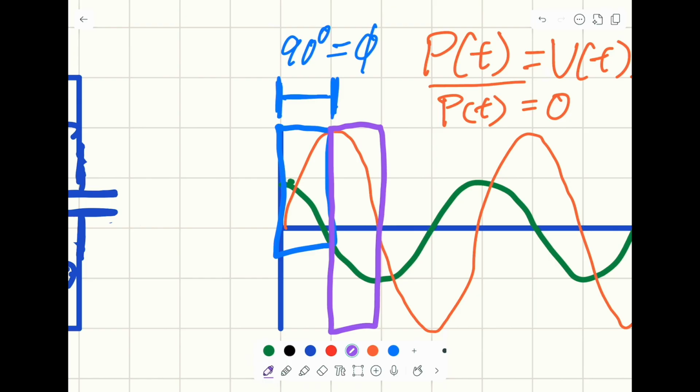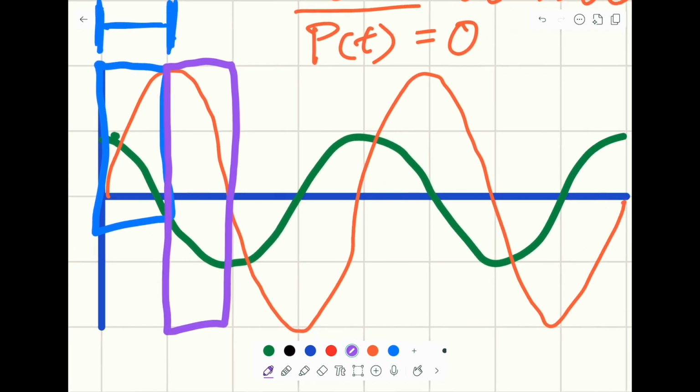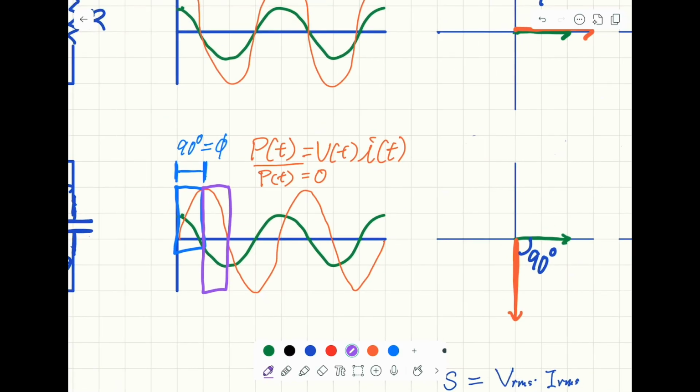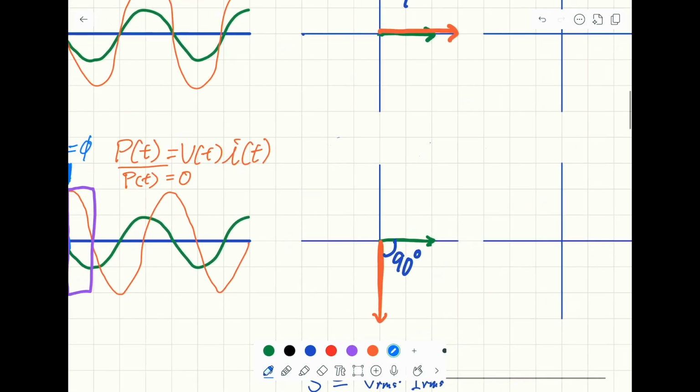And if you go through the mathematics, you will see the power stored in the capacitor is the same as the power released back. So the overall is 0. You can analyze the curve similarly. What I mean is there's a period of storing energy and a period of releasing energy. Now we can look at a couple more definitions in the phasor here.